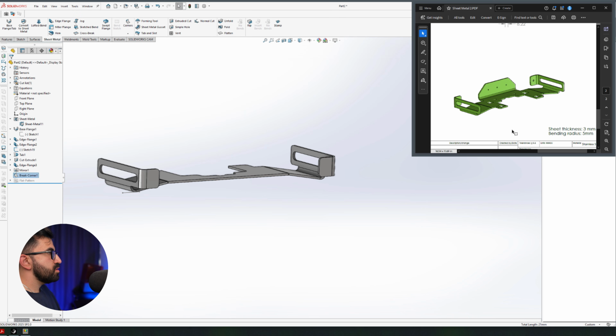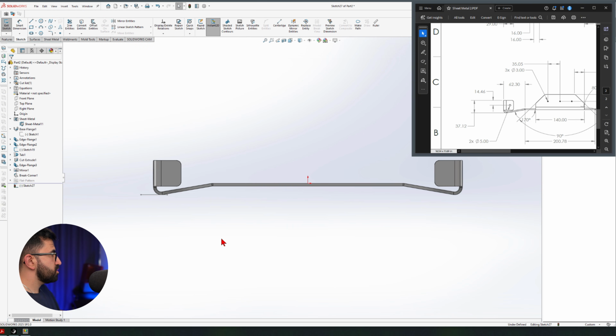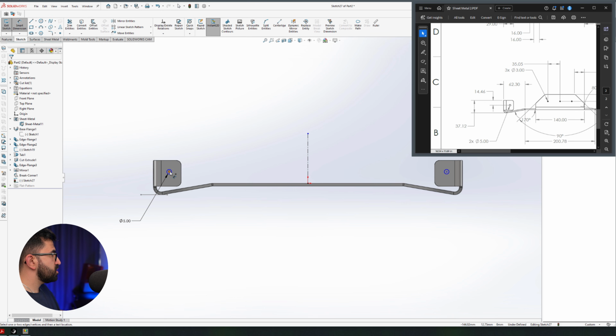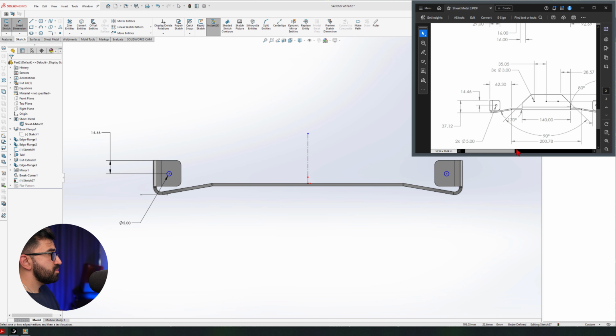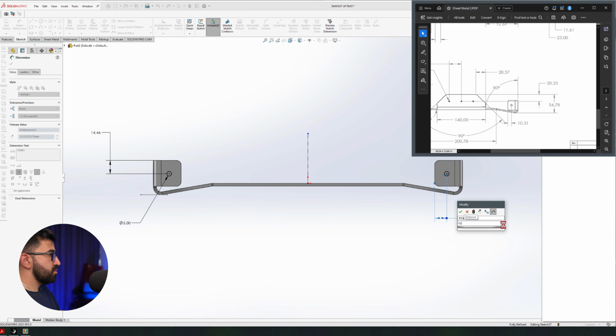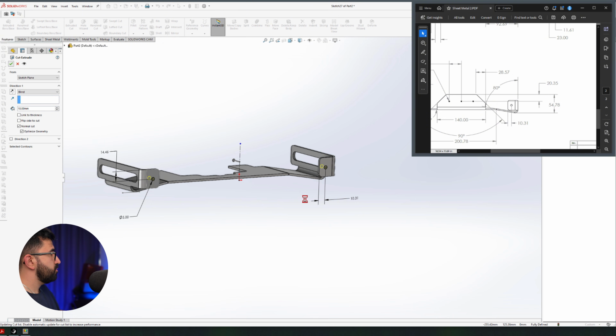Okay, we're still not done. We have 2 holes over here, radius or diameter 5. So new sketch, circle, center line, select them, mirror them, diameter 5, height 1446 from this top edge, and distance 1031 from here, 1031. Now I can just do a normal cut and ready.